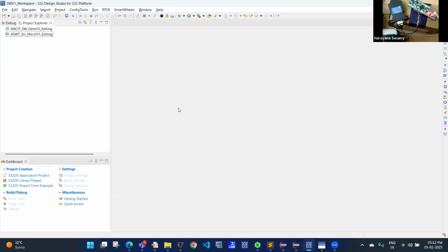Now, the second thing, assume that you want to read data from an ADC. There is a potentiometer here. If you want to read the potentiometer data, you have to enable the ADC and start sampling it. Normally, if the ADC is 12 bits, the data converts to 0 to 4095. Then you have to filter the noise, as there will be a lot of noise in the ADC signal. Then normally we scale it up. We call it mapping, or scaling.